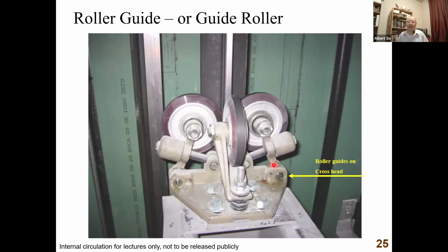So when the car reaches the landing, the mechanical linkage between the car doors and the landing doors is set up. Okay, and then when the car doors are open, landing doors are open automatically at the same time by the mechanical linkage. And when the car doors are closed, the landing doors are closed at the same time by the mechanical linkage, right?